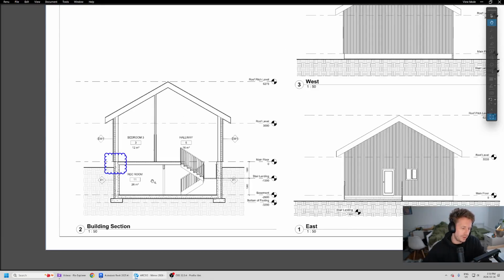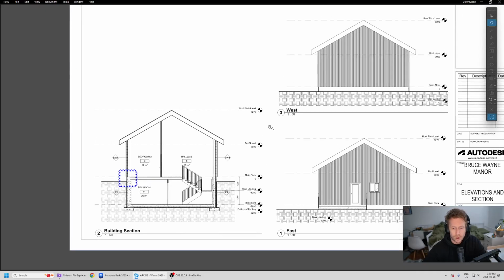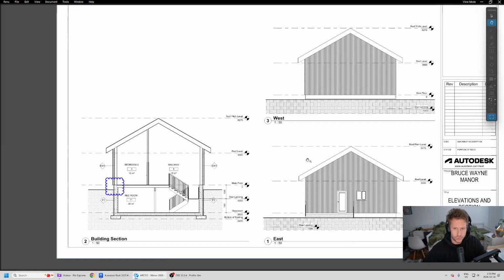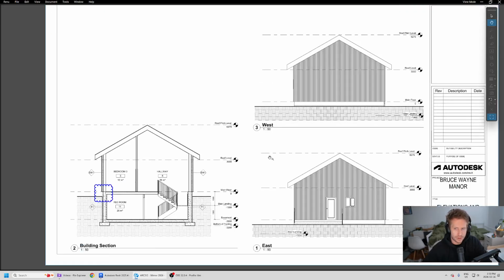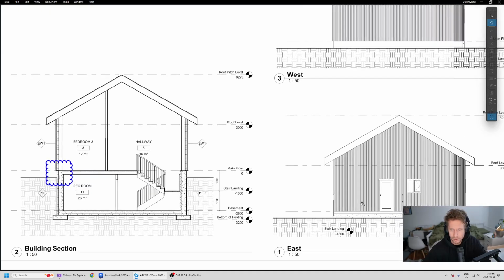We used to have a topo surface, and that's basically the top side of the earth here. And then they'd have something called a building pad, which was really intuitive, I think, up until 2023, really great. The Toposolid has replaced this tool, which I am not a fan of, but it's what you got. So that's what we got in Revit here. I would say it's not the most intuitive of the tools, and I'll walk through a little bit of what we're going to do here to get our drawings looking a little bit more like the example here.